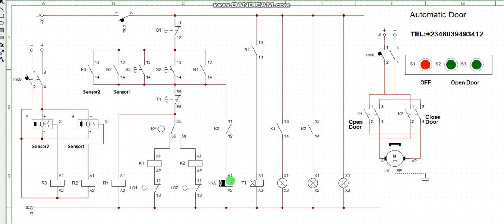So I use this particular relay to open the door and also close the door. Opening of the door is the on-delay function. Closing of the door is the off-delay function. I use this relay to energize these two contactors. For me to energize this contactor, how long the function continues depends on this particular relay. This on-delay de-energizes the function of this on-off delay. I repeat again, for this contactor to close and open, the device responsible for this function is this on and off delay.